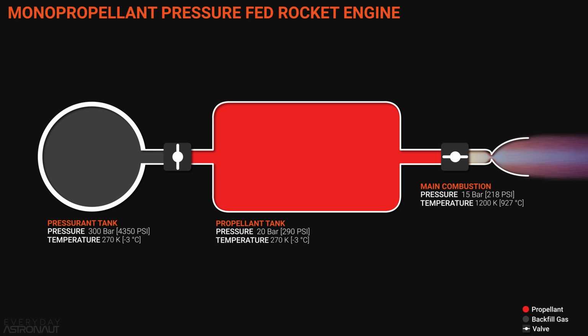But another good thing is now we can use a denser liquid propellant in our fuel tank and keep that fuel tank at relatively low pressure. It just has to be higher pressure than the engine. So as liquid fuel is drained out, we backfill the voids and keep that fuel tank pressurized with the pressurant tank. So we gain efficiency in a few ways here.